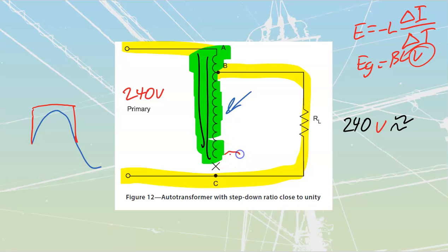So what you could see across here is you're going to see arcs and things like that, high, dangerous values of voltage that can sometimes be tens, if not hundreds of times the actual size. So if you get one of these where your transformer is loose, is open on the inside, you've got to be careful because you're going to get stung. Low current, but super high value voltage. It's going to be like having barbecue igniters across your fingertips. It stings super high, and thankfully it's probably going to travel across the surface of your skin, but still, it's going to be an electrical hazard.